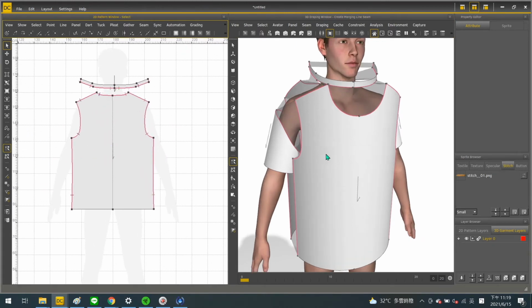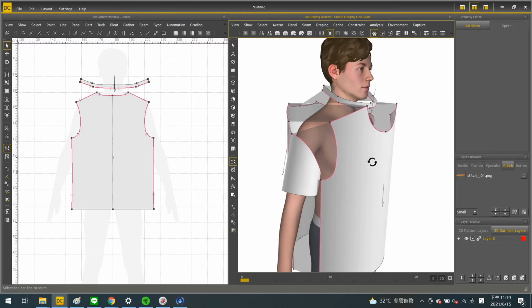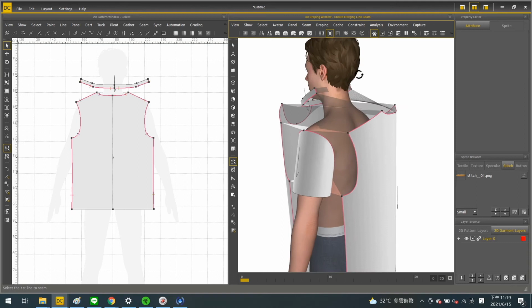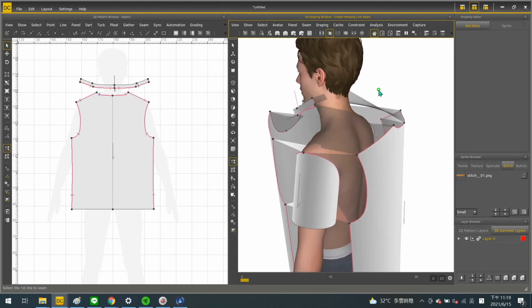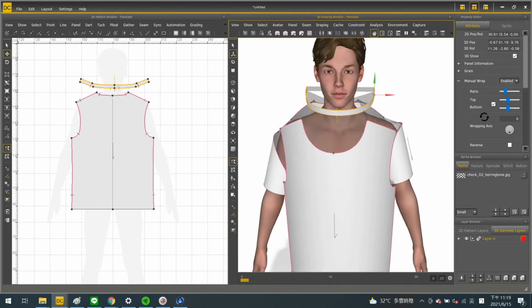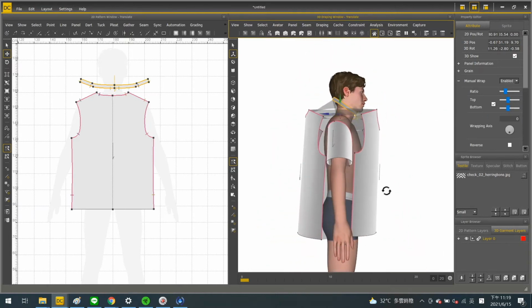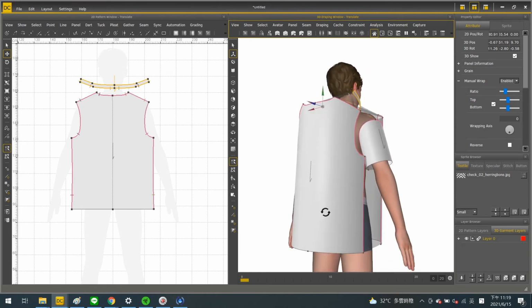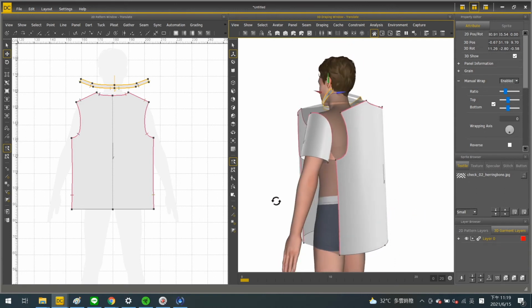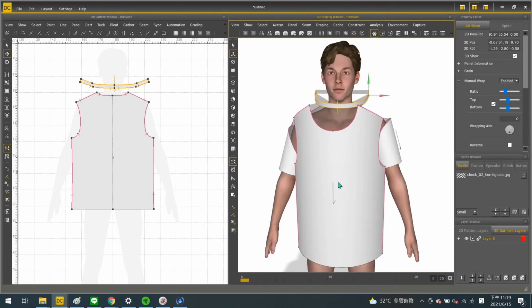If all seams are already made, then we can check in the 3D window. The rule here is that the body shouldn't penetrate through the same surface. So for example, like this, we can adjust the position of the panels and make sure all the panels and seam surfaces completely cover the body. At that stage, it means our preparation work is done and we can start with simulation.